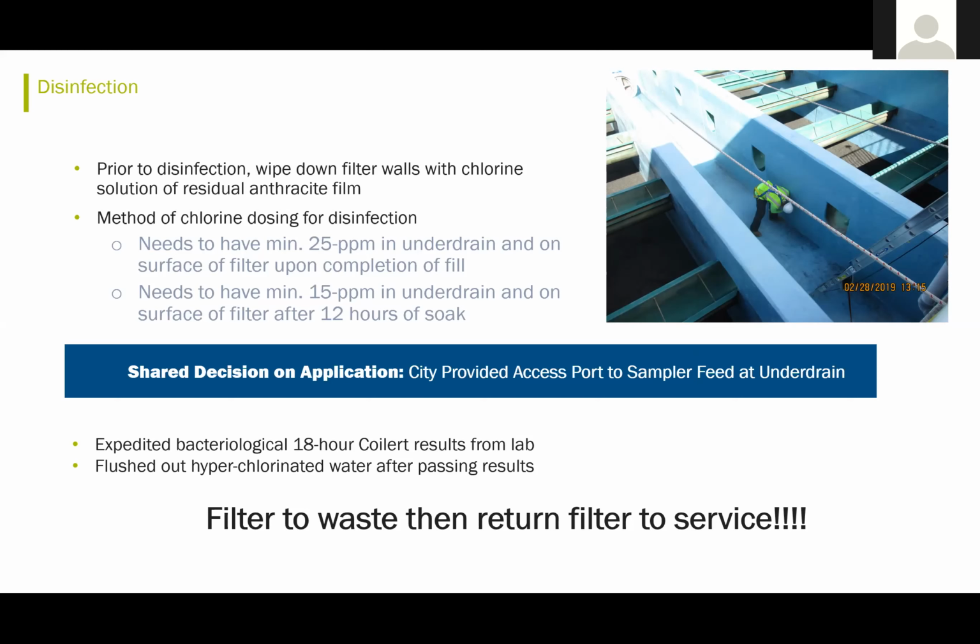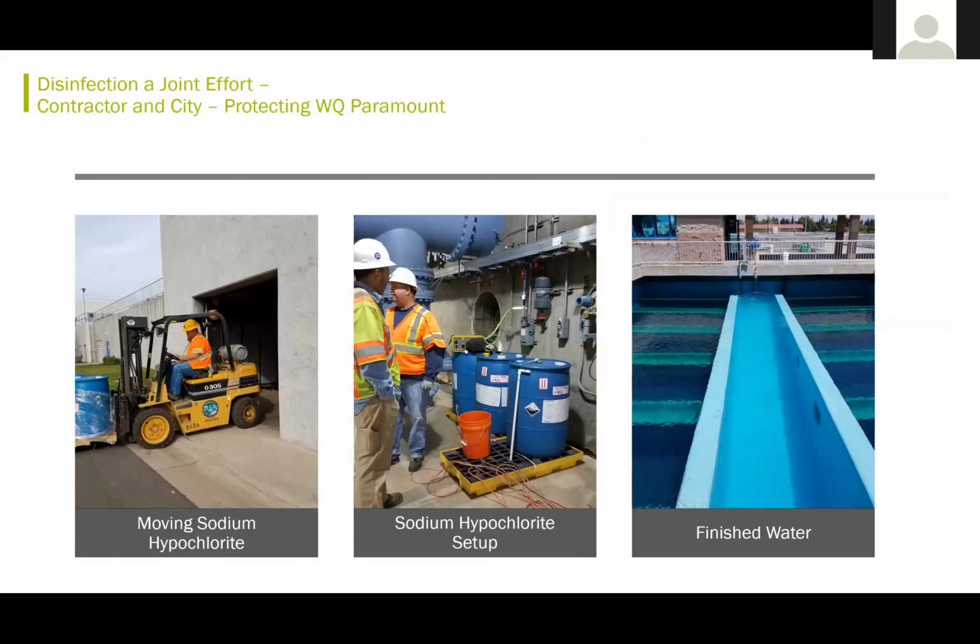On the initial disinfection effort, they failed the bacteriological test. And so they revised their methodology somewhat and changed the disinfection point. And the city was using an 18-hour cold alert test so they could expedite getting the results back to the contractor. And then they flushed after disinfection, and then filtered to waste and returned the filters to service. So just some shots that were taken when they were setting up to install the disinfection process.